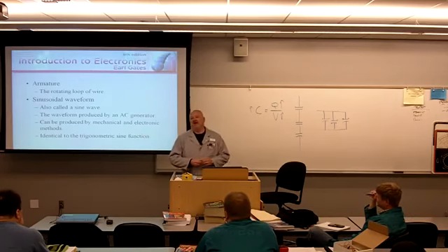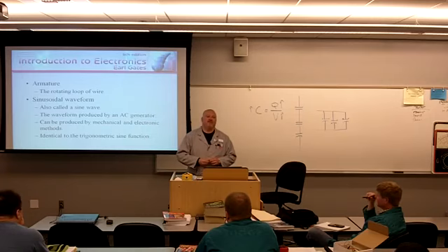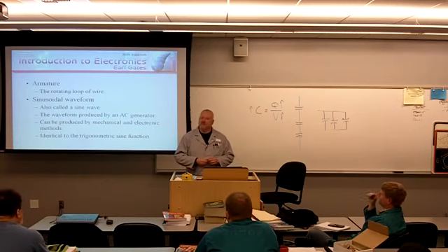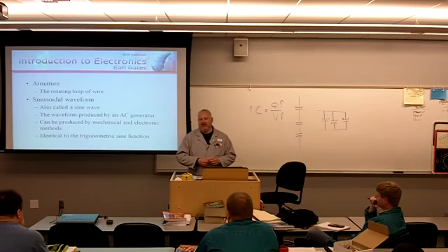The only problem with the aviation APUs is they produce 400 hertz. They don't produce 60 hertz. Aviation uses 400 hertz systems. Why so high? Precision. The old navigation systems needed cleaner power. And on board aircraft specifically, they have what's known as an inertial navigation system.